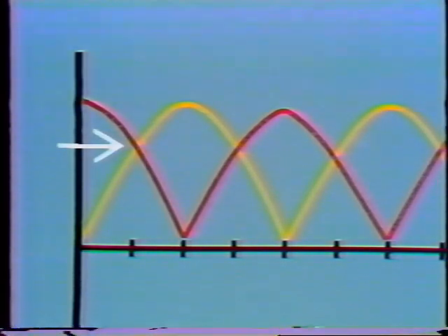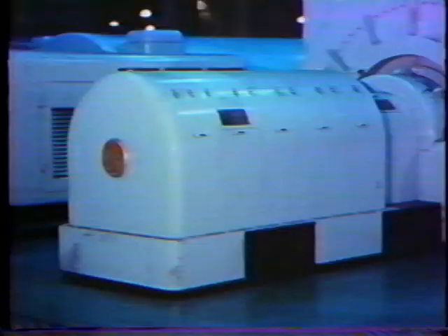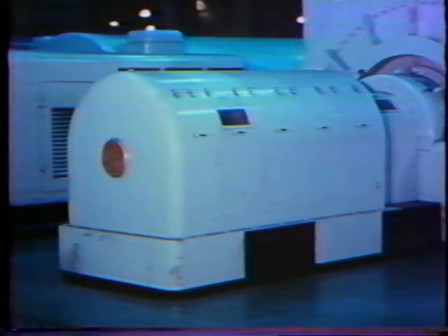If we could add more and more loops and reduce the ripple even more, then the output voltage would become very nearly steady DC. Remember, though, that for every separate loop we add, we have to add 2 more commutator segments, too, one for each end of the loop. Real DC generators have many loops and many commutator segments.